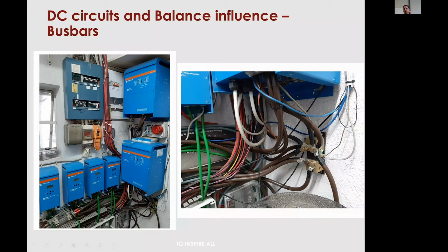That becomes a preferred path, and the last lug does not. And so even though it's all on the same thing, and even though it does not violate your DC theory, in other words, all of those things should be seeing the same voltage and the same current, you actually have set up preferred paths, and the least resistant path is the path that the current would dominate on.